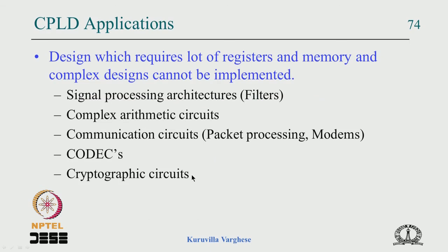So I think we have come to the end of the CPLD. What we have seen today is basically the CPLD architecture, how a hierarchical PLD is formed out of simple PLD sections. So there are logic blocks, a crossbar which interconnects, which allows the output to go to the other inputs, IO pins to go to any of the inputs, and then there is a product term allocator which allocates it for various things.